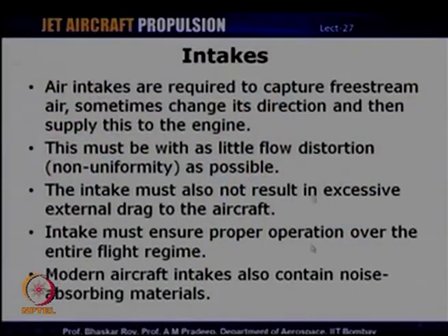So, air intakes, of course, the primary function as I mentioned is to capture free stream air, and in some cases also change the direction, which I will explain shortly, in that in some cases the intakes are curved because the engine is located at a different axial location, and therefore, it has to turn the flow, change the direction and then supply that to the engine. But this must be done with as little flow distortion or non-uniformity as possible. We will quantify flow distortion in the next class, how we can measure and put a number to flow distortion.